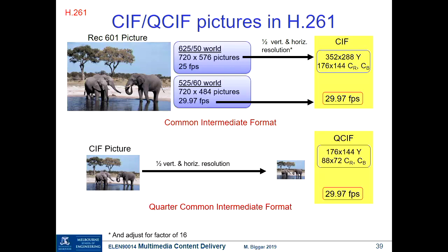Yeah. Where's the 29.97? Oh, okay. It's a hangover from the analog days. The nominal frame rate in the US was 30 Hertz, but if I remember this correctly, because it's stuff that's kind of history now, when they introduced colour, there was an additional carrier signal put into the analog television signal, and because of possible interference issues between this colour subcarrier and the audio carrier, they needed to shift timing a little bit, and so it turned out that by changing it by a factor of 1/1000th, they solved this problem. So that's why 30 Hertz became 29.97. So it's kind of historically interesting, but it's gone into the past now because we're all digital these days.